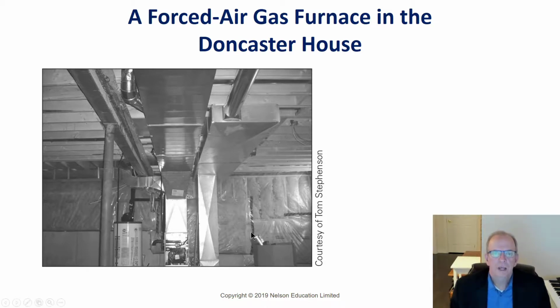So it's not quite as comfortable, I would say. So the hot air system, the hot air ducts, what we call the supply ducts, come off the top of the furnace. The ones going to the bottom of the furnace are the cold air return. When the warm air is heated, it's blown with a blower fan, and that puts enough pressure to move the warm air to the particular rooms where the ducts come out of the floor, the supply air, to heat those rooms.